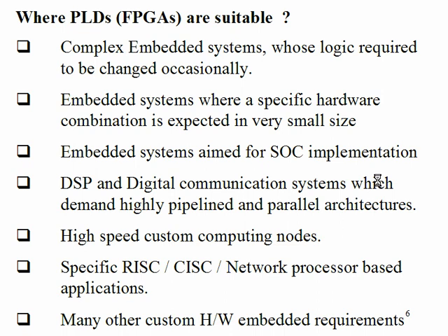FPGAs also come with a RISC processor in them. That means an FPGA internally will have a processor. Today you have an FPGA which has 4 processors. You also go to the extent where you have 16 processors in it. Along with the logic cells, I/O buffers and routing channels, internally it will have 16 processors. Those processors are implemented in hardware, not by writing VHDL code and putting it on top. That is called a soft processor. These are called hard processors. You got the point now?